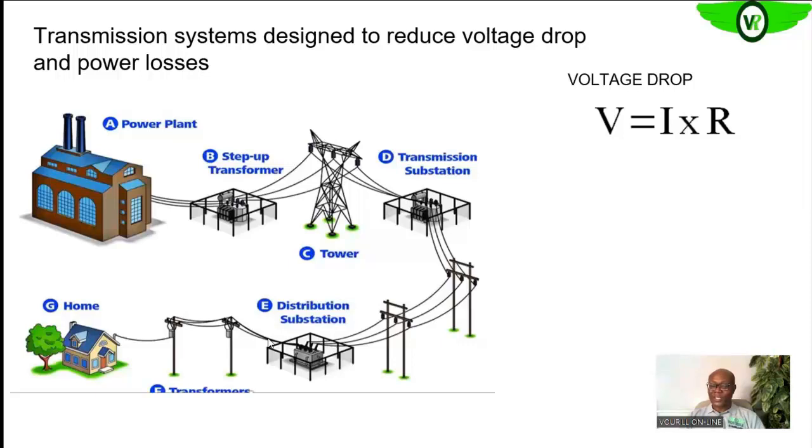We'll be having, say, 300, which means phase and neutral will be less than 180 fed to our load. Okay? So all of these are not desirable conditions like we said earlier. So we need to minimize that voltage drop as much as possible.